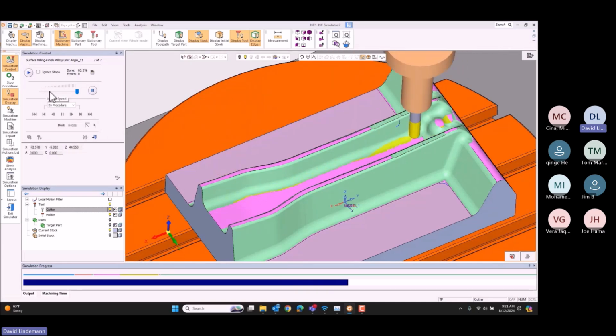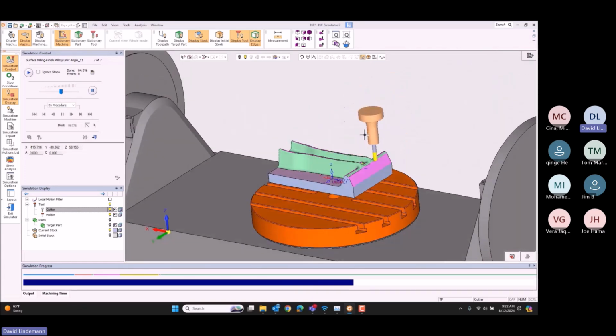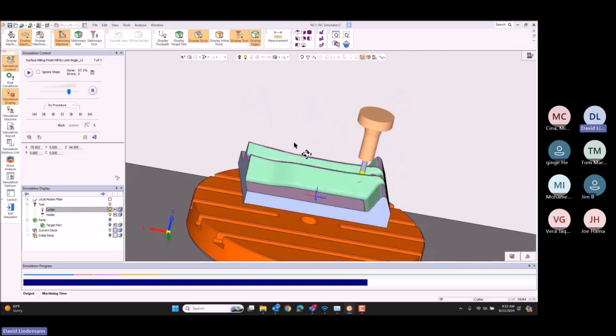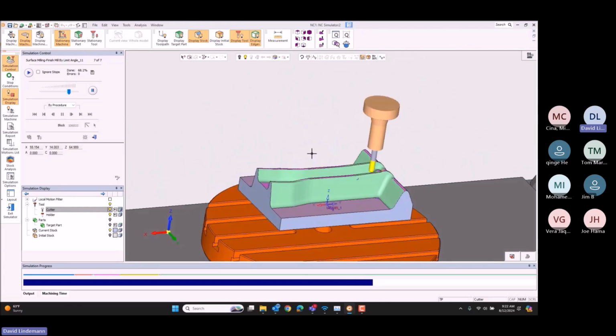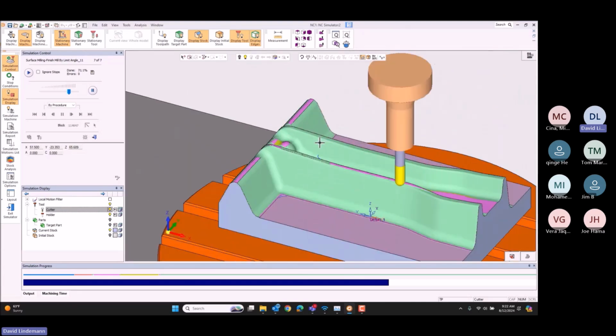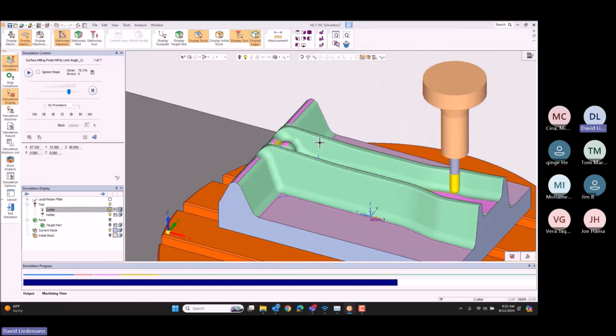And it's not necessarily that the job has to be this particular shape, or a similar shape. It could be something different. It just needs to use the same tooling series, which typically I'm going to rough similarly, if not the same. I'm going to do the same kind of semi. Now all that's left is corner picking and then getting back in there with the finish. And you can see how it's separated in the finish, those Z levels working its way down nice and clean. Now it's going across the tops, staying on the top. And then you'll see it go down and take out the middle area.